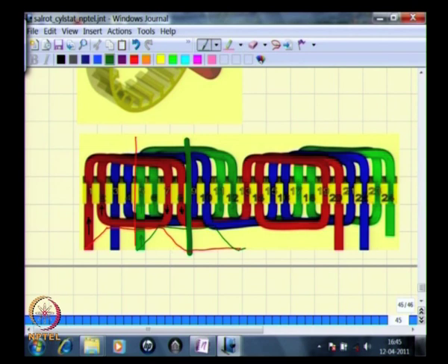And now you see that there is a separation between the axis of these 2 windings. These 2 windings will generate maximum MMF along 2 different directions if excited. What we are now interested in is assuming that the R phase winding is excited, we know what is the variation of MMF around the air gap.